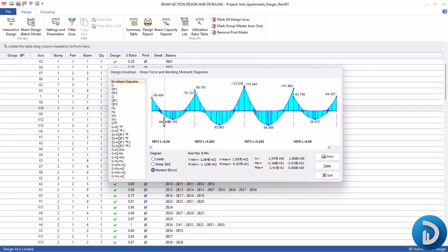This is the part where we have 4Y16, and the minimum hanger bar provided at this top zone, because it experiences minimal moment, is 2Y16. Moving away from the 2Y16, the reinforcement that will be able to counter this moment effectively, I think 2Y20, was provided at this point, separate from the 2Y16. So this is how you can relate this to the reinforcements provided by the design software.